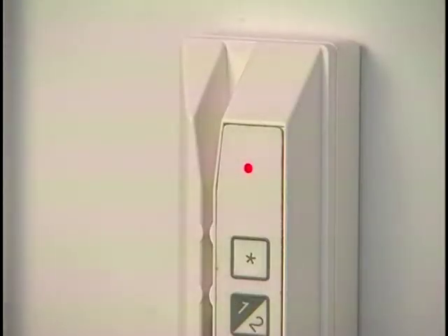Most readers have a bicolor LED and a buzzer for visual and audible feedback. The LED will flash in different ways to indicate different things. A steady red indicates the door is locked, and a steady green indicates the door is unlocked. A slow flashing LED, twice a second, indicates the partition or partitions the reader is assigned to are armed. A medium flash, 3 times a second, will occur after a wait for privilege card has been presented.